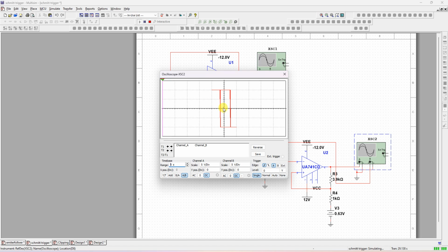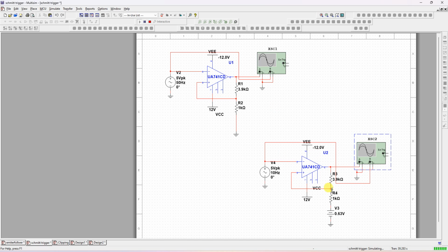Okay, if you give more frequency, 1 kilohertz, you will get many lines here. So try to give less frequency. Here I gave only 10 hertz. So this is Schmitt trigger, which compares input voltage with two reference voltages, and here we are using one more reference, but this one is a Schmitt trigger without any reference voltage.